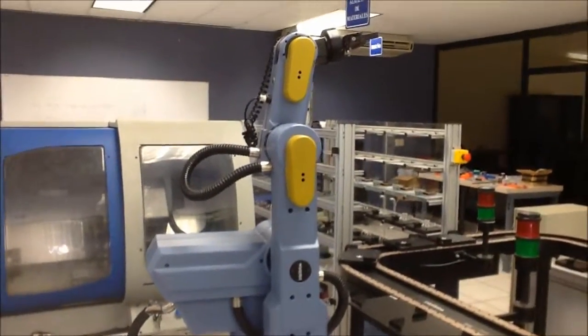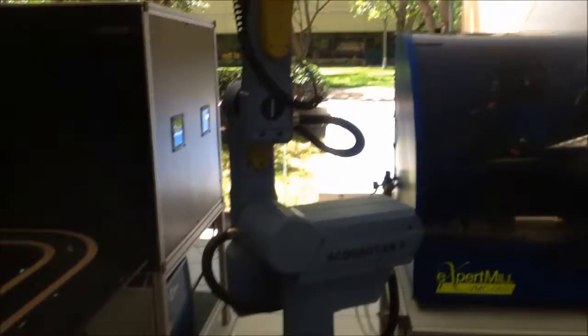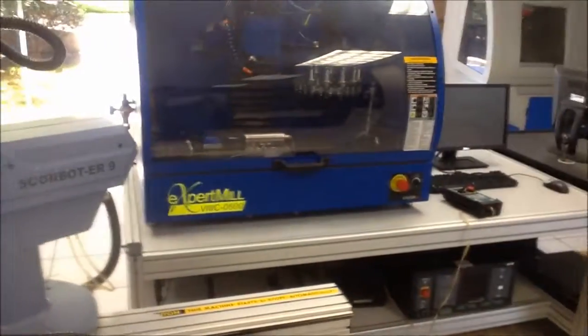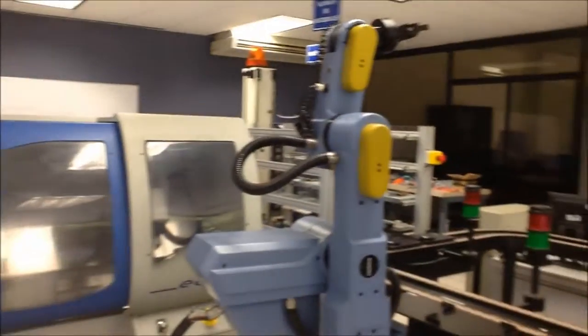These are the anthropomorphic robots. There are 2 in the whole manufacturing cell. Having 6 degrees of freedom, these robots take the part from the conveyor and hand it into the lathe or the milling machine, so they can begin with the work. When a piece has finished its process on the lathe or milling machine, the robot takes it to the conveyor again.